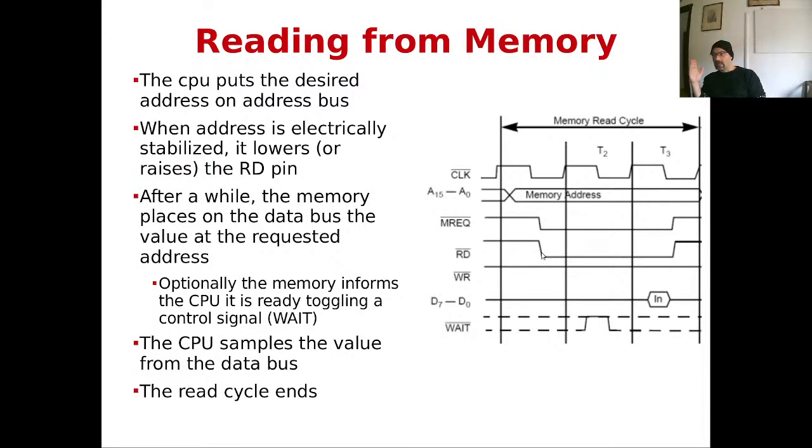And then after you have done that, you typically have to wait a little time for the RAM to respond and to put as output in the data bus the value of the cell that is written in the address bus. So after a certain time, in particular one machine cycle, here you see this sausage, which represents a change in the line D7-D0, which is my data bus.